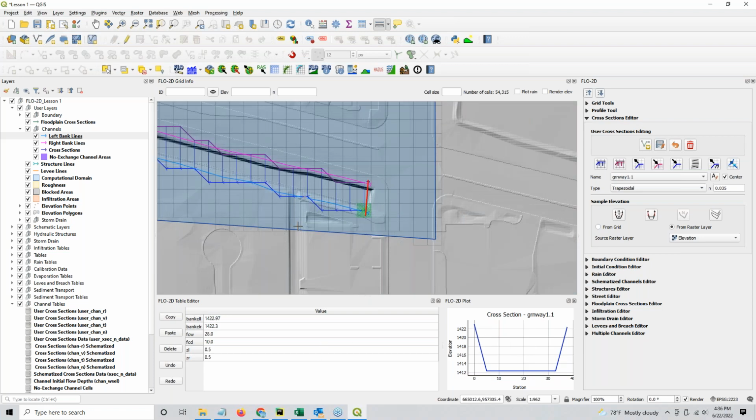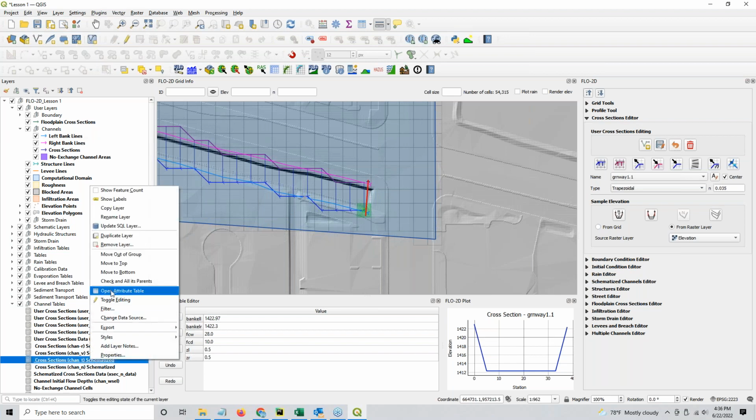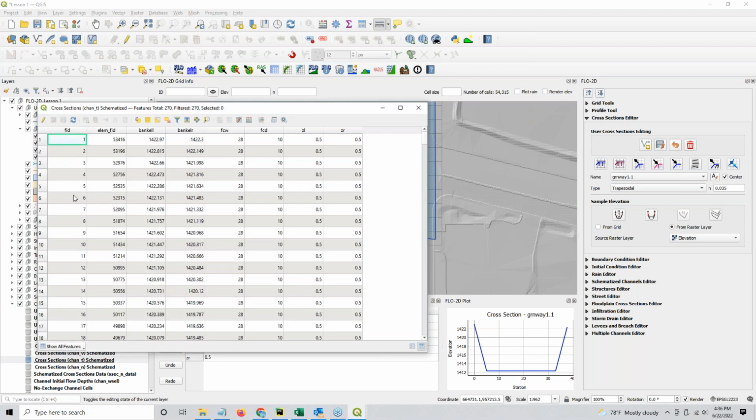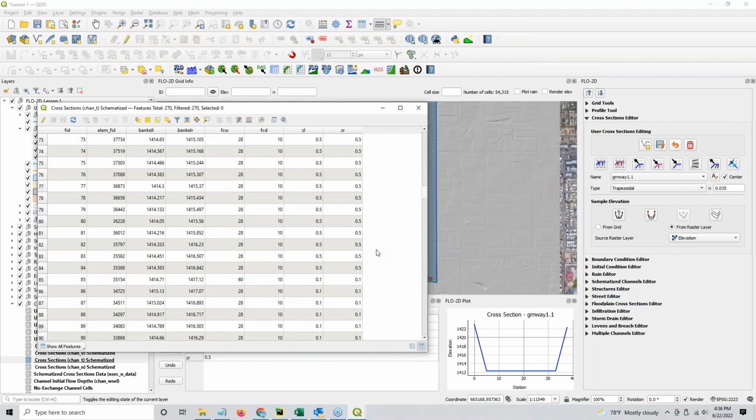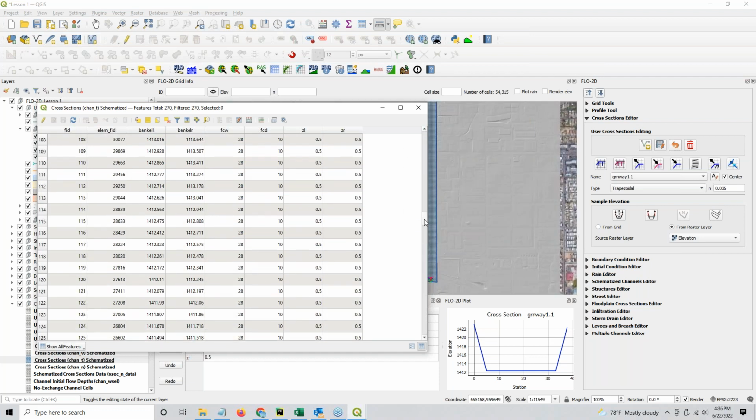And then the next thing you'll want to do is run the other interpolator. This is the prismatic interpolator. So you run that, and that interpolates the prismatic data. It's basically just the bank data. So if you come in and see your schematized data, what you might see is that you are getting interpolated bank data, which is pretty sweet, but you're not really getting interpolated this stuff.